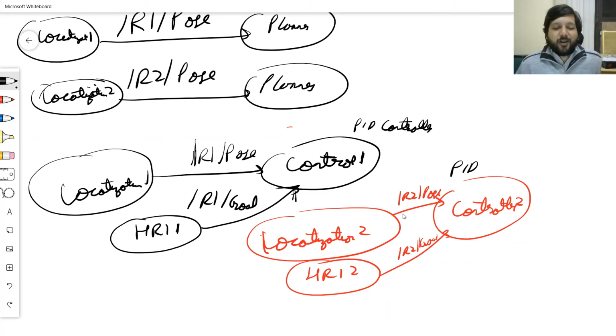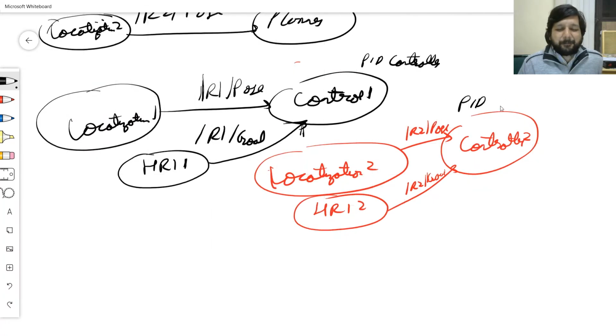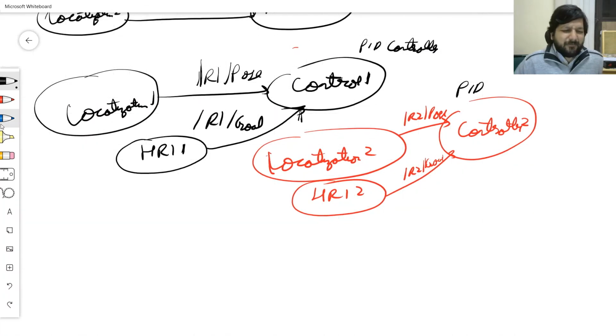We are doing some swarm behaviors that now we expect to do using ROS. And if every robot has its own controller, then we are talking about too many files. So far, we just had one controller, and by changing the parameters in a loop, we could control all the robots by using one control algorithm alone. So one of the ways to handle this is what's called remapping.